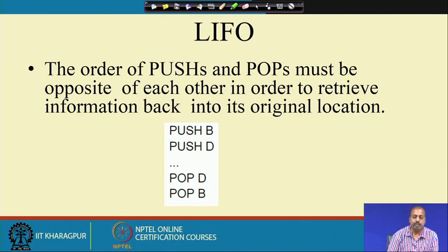Stack works in a LIFO fashion, last in first out, because the basic 8085 designers have not put any restriction on the order in which you do a push or pop operation, but as a user of the system, we have to be careful. The order of push and pop must be opposite of each other in order to retrieve information back into its original location.